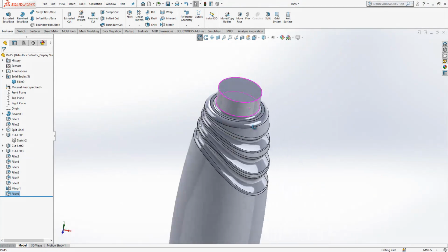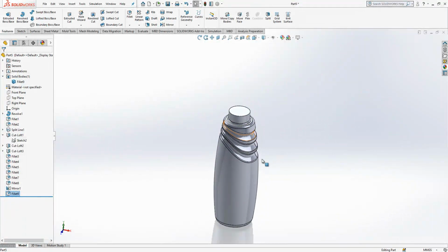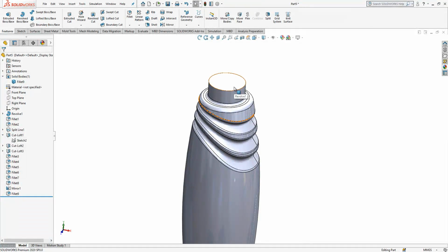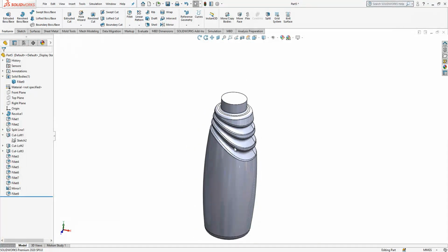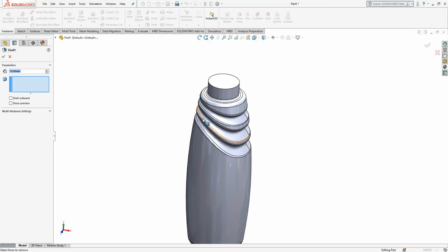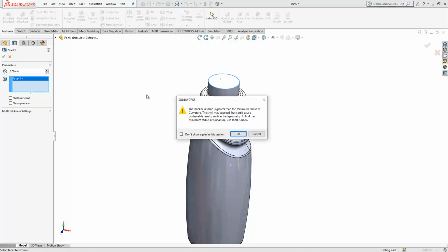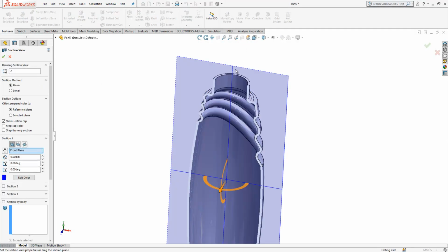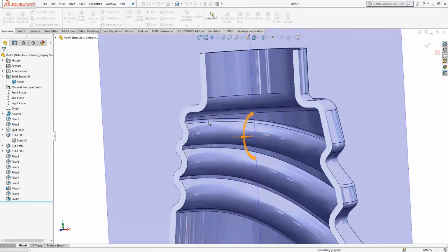Normally, guys, when you design plastic objects, the material that you are using is very important. You need to know critical material thickness, how thin or how thick you can make it, because these are not limitless things. And based on that, you can also define your radiuses. For example, let's say this has 2 mm of thickness. We have at some locations 2 mm thicknesses. We get an error. It says, in fact, in some locations inside, you do not have any more radius.